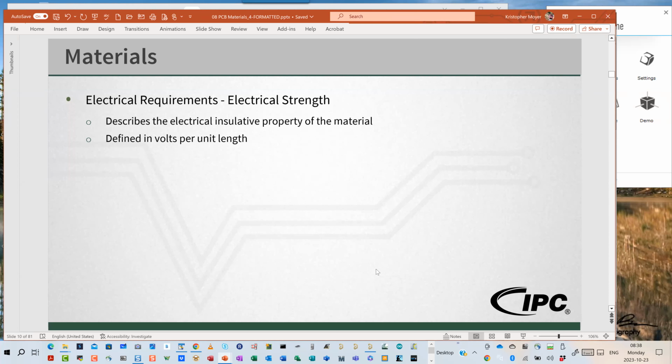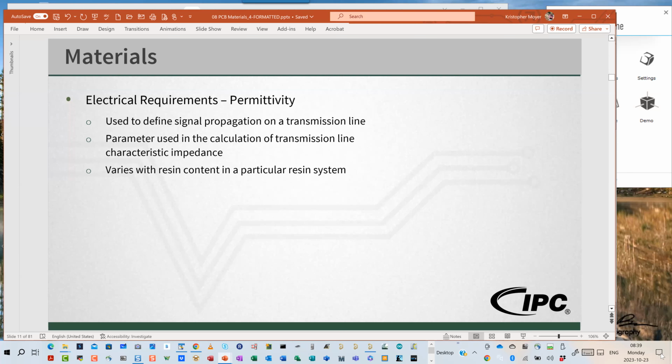We will actually rely on these electrical strength definitions quite a lot when we design our stack-ups in order to overcome or mitigate some of the statements in our 2221 voltage chart, especially when it comes to Z-axis.